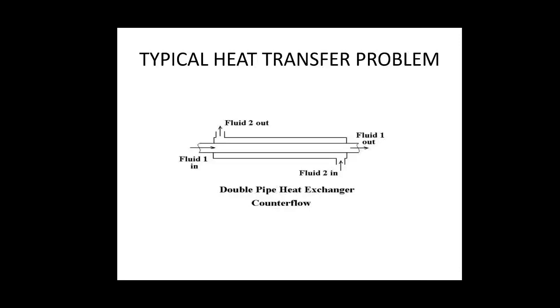Okay, so before disposing of the chemicals, let us say you want to cool it off, or even you can say before going for the chemical reaction you want the chemical to be heated. In either case we can employ a heat exchanger, or counterflow heat exchanger to be precise, like this. That means in one pipe cold fluid will be flowing, in another pipe hot fluid will be flowing.